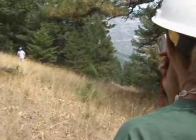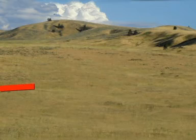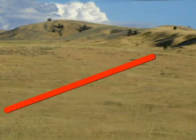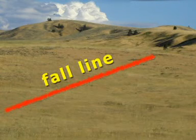Calculate the half rule whenever the terrain changes. Always follow the half rule, even when working on gentle slopes. You may be tempted to exceed the half rule when grades are low. But if you exceed the half rule, you'll be designing a fall line trail that will erode.